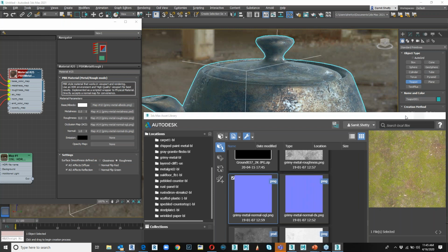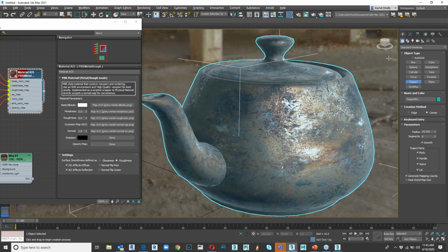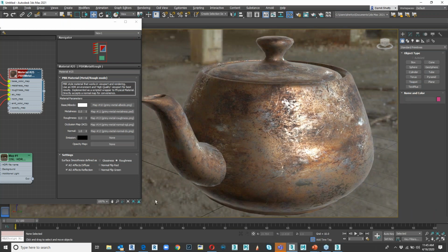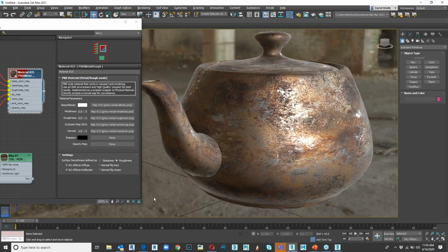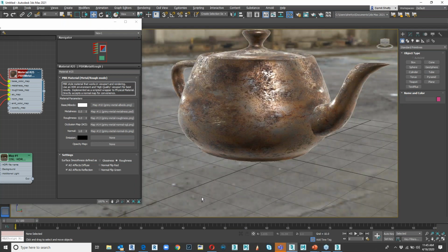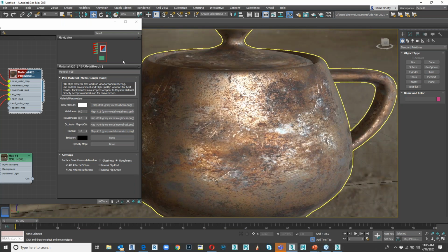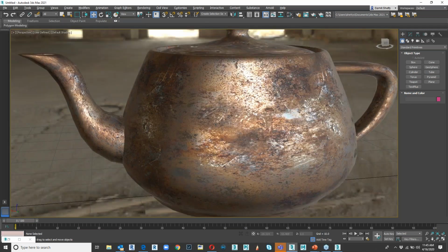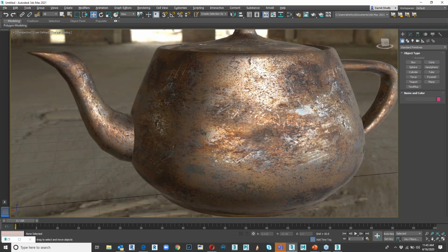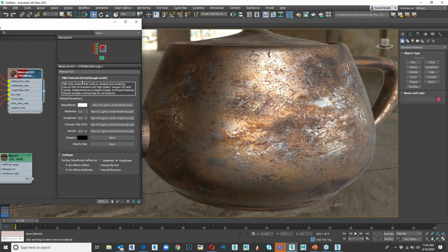No harm in it, but you can see how you have this shader being created, which has a complete rusty metallic look. And not just that, if you want some more reflection and stuff like that, you can very easily go and apply reflection. For example, you can just increase the metalness of this, or reduce the roughness of this, and so on.